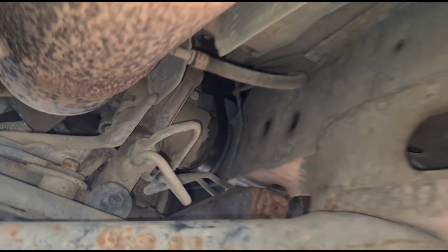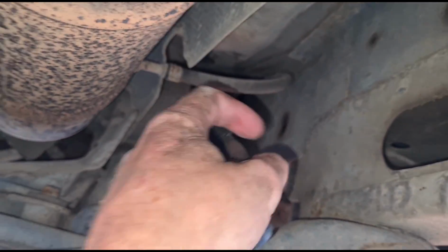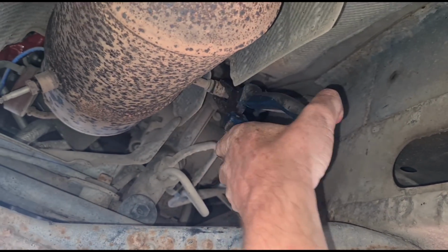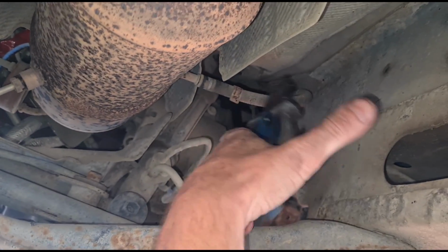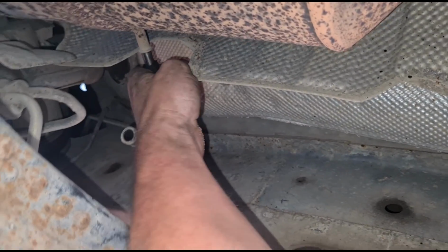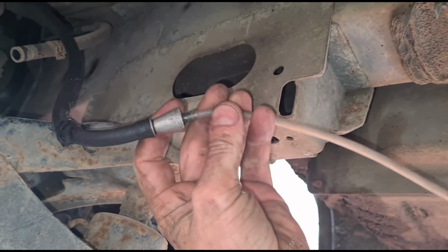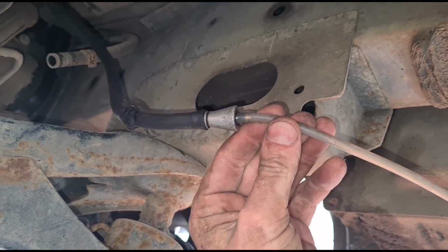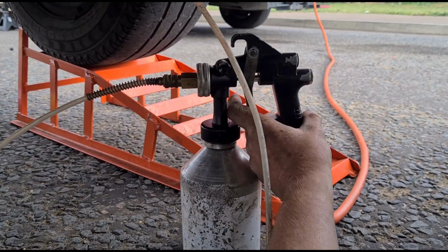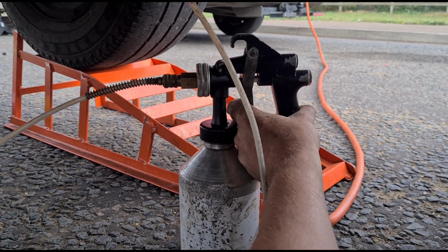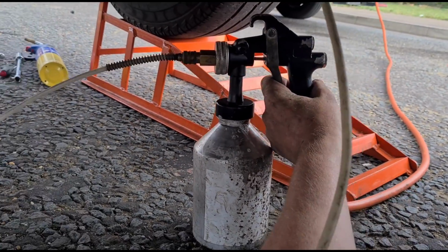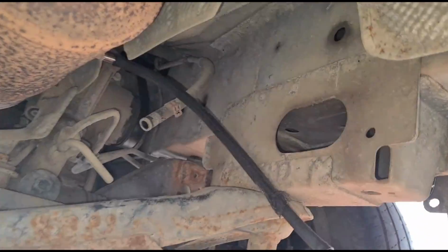Okay, back under the van, we'll come over here and we have the DPF pressure sensor hose. We're going to take that off, and then we can access into the DPF with our pressurized gun. Remove the clip and remove the hose. Now I'm just going to push on my own bit of fuel hose here. That's connected to my cone, which is connected to the gun, and the gun is connected to a pressure compressor. This is set to 131 psi. Just get that bottle sealed up properly. So we're squeezing all of this fluid directly into the DPF right up there.